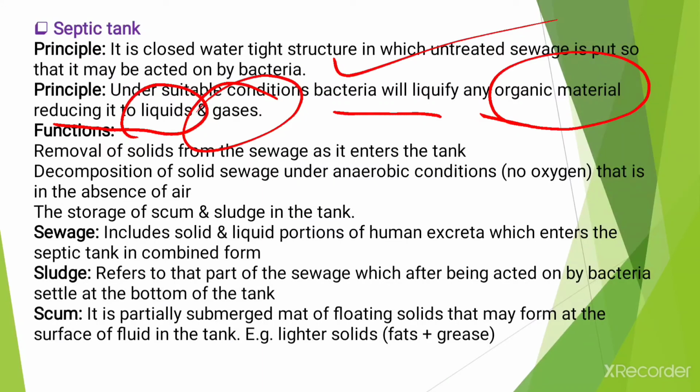Then what are the functions? Removal of the solids from the sewage as it enters the septic tank. Then decomposition of the solid sewage under anaerobic conditions, meaning without oxygen, that is in the absence of air. And the storage of scum and sludge in the tank.